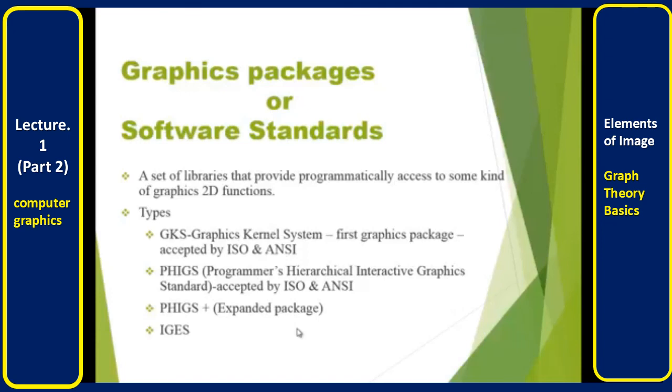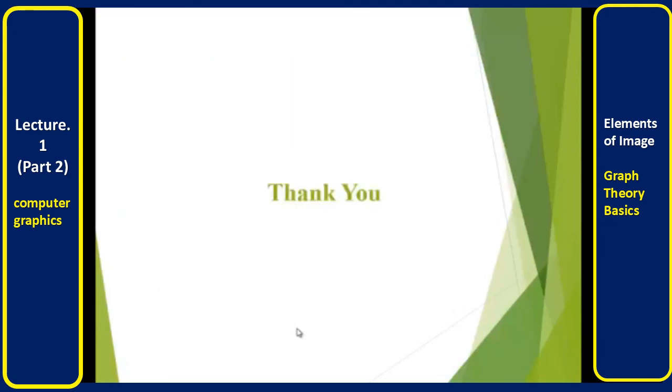And the third one I mentioned, Initial Graphics Exchange Specification, IGES. This standard is concerned with the storage and transmission of data between graphics systems and between graphics-based computer-aided design and computer-aided manufacturing systems.